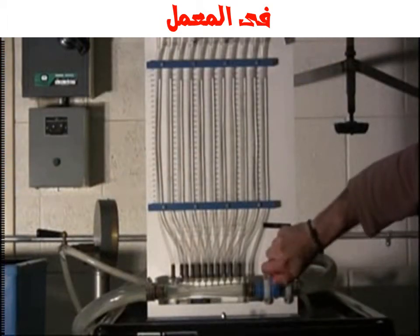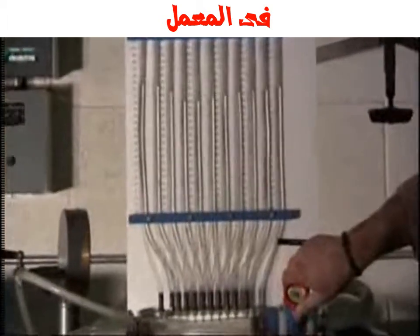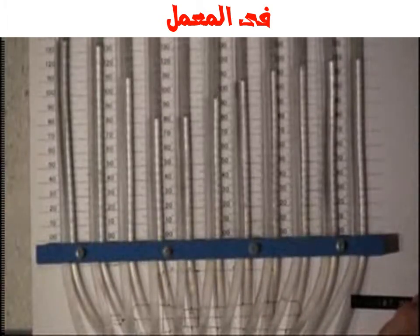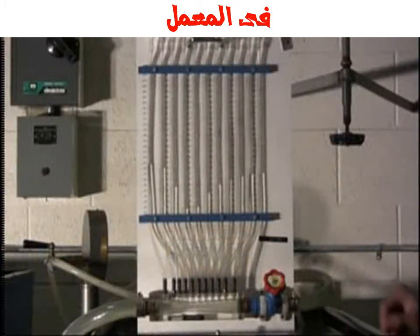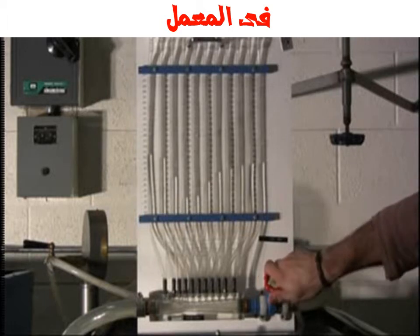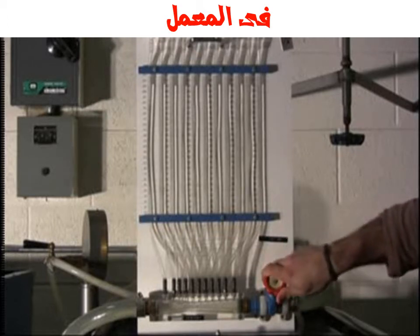Now adjust the flow to a higher discharge. Then record the piezometer readings and measure the discharge as previously described. Repeat the step for the remaining flow adjustments. After the last flow adjustment, turn off the flow completely by turning the red valve clockwise. This concludes the procedures for this experiment.